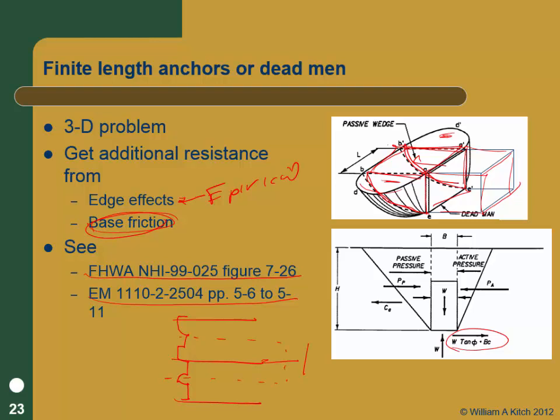And if you're going to put that back to a single solid dead man, make sure that you've actually got the total load from that area. You're not using some load per foot back here for your anchor block, because once you've decided you're going to use that single anchor and take it back to a single block, it's no longer a load per foot. It's actually a total load from that tributary area.